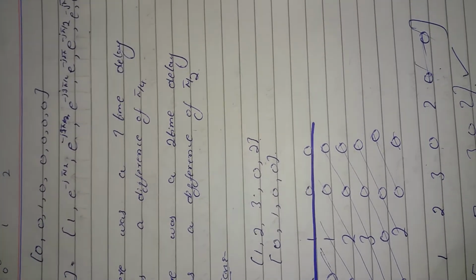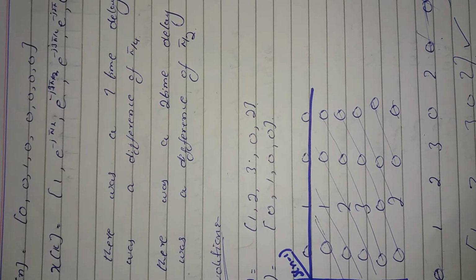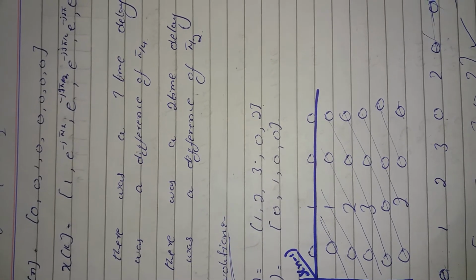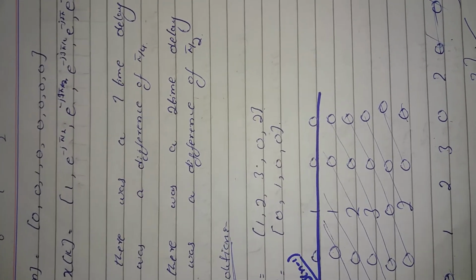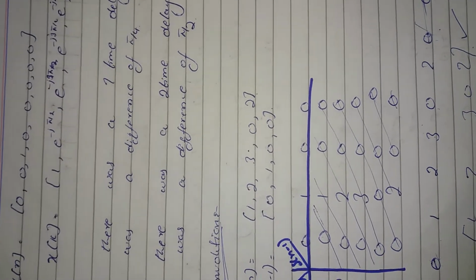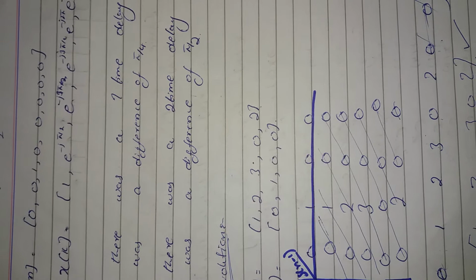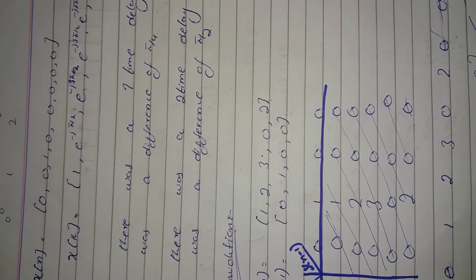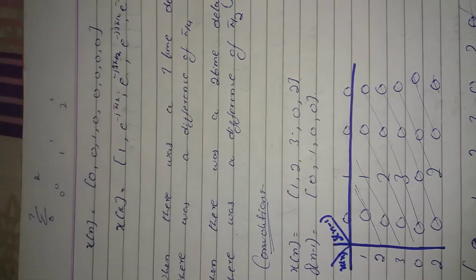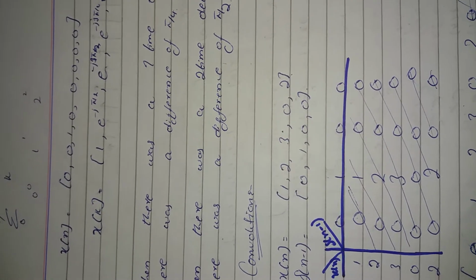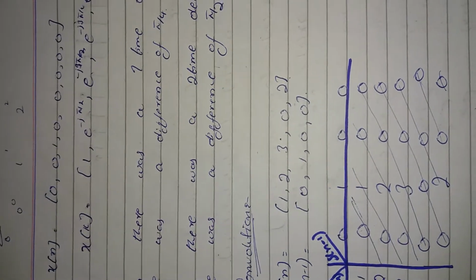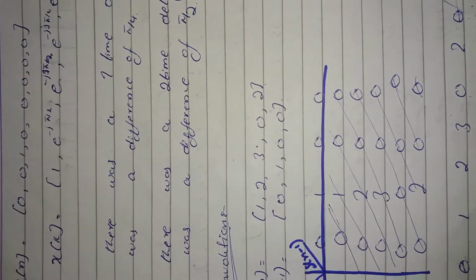And in signals and systems we ask what is the effect of one signal on the second signal, so that it can create a third signal. And what we do in convolution is that if we have two signals, we mirror one signal and then pass it through the second signal by multiplying it. So the signal that we get will be the convolved signal of those two signals.